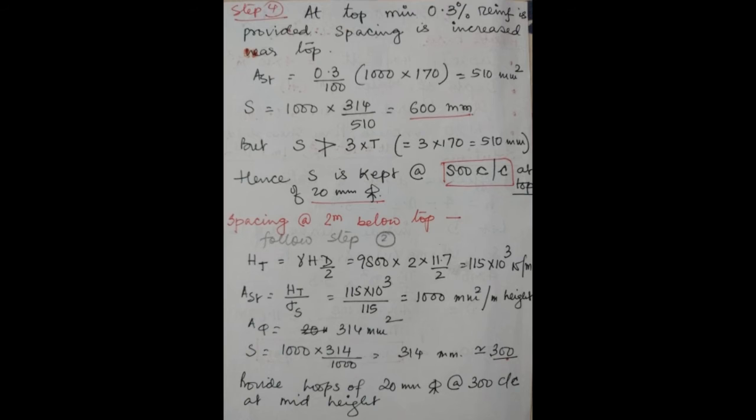Okay. Now see, as I have explained earlier also, at the base, as it is a flexible base, the diameter increases, and also the hydrostatic pressure is the maximum. At the top it is less, so it will be economical and judicious for us to provide the same diameter bar, but provide it economically by varying the spacing of the bar.